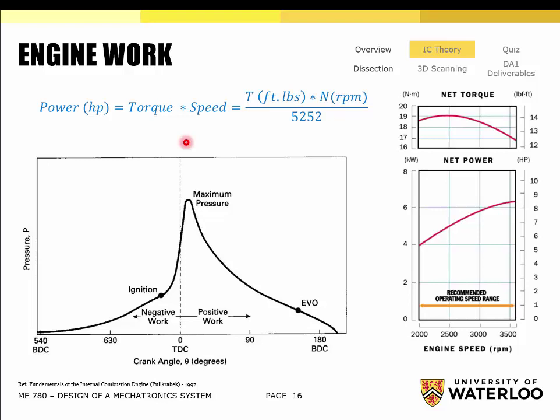It's a similar thing with the engine. If you time it so that the push occurs about 12 to 15 degrees after the peak, that's when it actually does the most amount of work. And the reason for that is the area under here is maximized. If you move this to the left, you're sacrificing all of this area that is doing useful work. So it's not that good, okay?